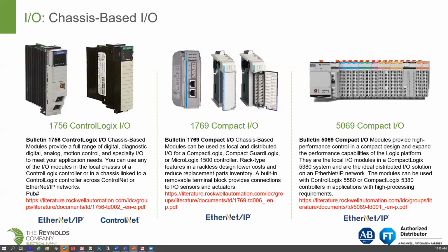It's a nice IO, good footprint, nice price point, but we're not seeing people use it as much for remote IO nowadays because they're more pointing towards its partner next to it, the 5069 Compact IO. This is the IO that is based for the newer controllers, again the quad core.